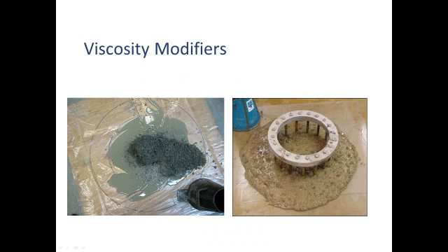This is another photo of self-consolidated concrete that's made improperly. So this may be just a conventional mix on the left that had polycarboxylate added to it. And you can see the cement paste, in this case just cement and water, leaking out like latex paint. And then you're left with a pile of wet rocks. Whereas on the right, that's what it should look like. It's one of the tests to ensure SCC can flow through rebar obstruction, so it's a standardized ring. And again, you can see the edges look the same as the middle.